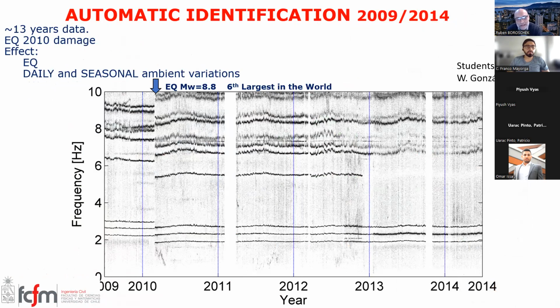And what we do is that every 15 minutes, we get an evaluation of the modal properties of the structure. And we have an automatic system that detects changes in these modal properties. And every time there is an earthquake, we also monitor the modal properties before, during, and after. And we also evaluate the interstory drift and maximum displacement. So in this building, because we are in Chile, we have recorded 1,700 earthquakes. Yes, 1,700 earthquakes, and most of them are quite small.